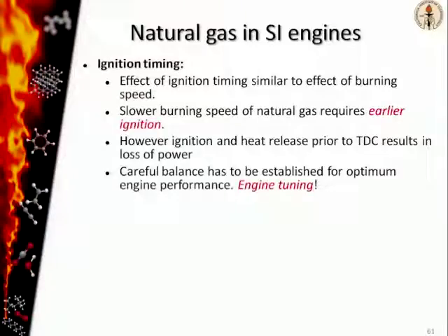But igniting too early in the cycle is problematic, because if you ignite the mixture at the point where the piston is moving upwards, you're producing high pressure inside the cylinder as the piston is moving upwards. So you're actually producing negative work. You're losing out on the work output from the cycle because you're essentially working against that high pressure generated by the combustion process.